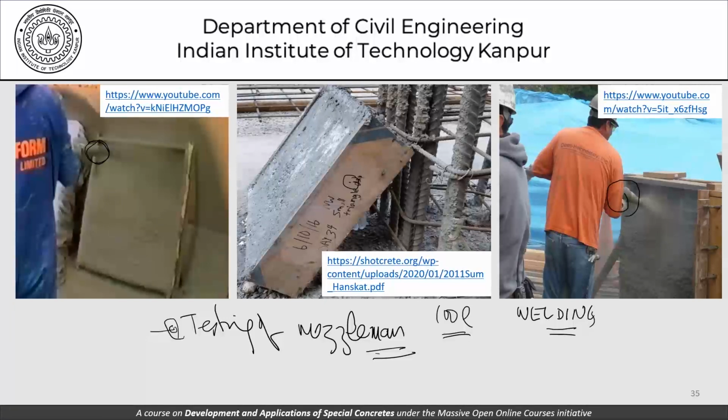But when it comes to a mock-up, it's a much larger exercise, and 100-liter mixers from the lab will possibly not suffice. And therefore, RMC plants have to be mobilized. So the entire team from different parts gets mobilized, creates the mock-up, and is better prepared to do the real operation.